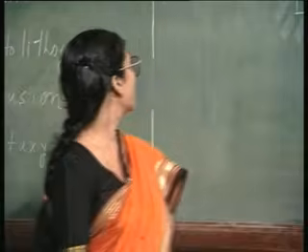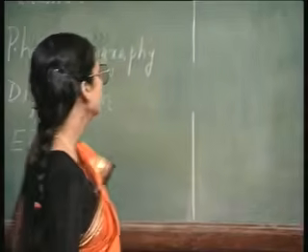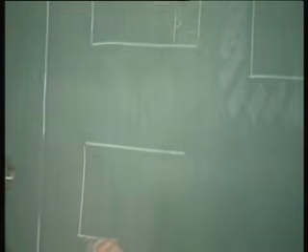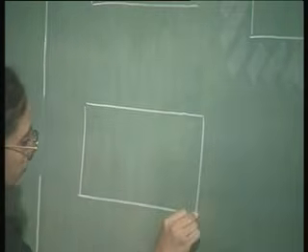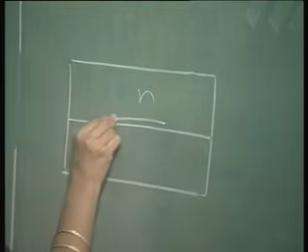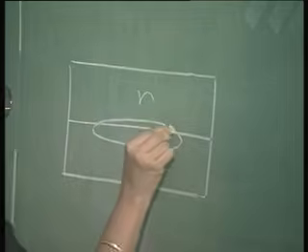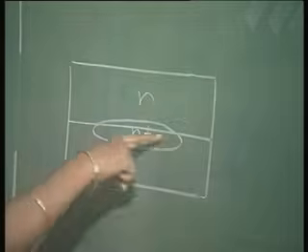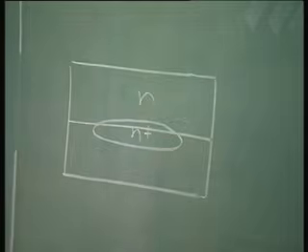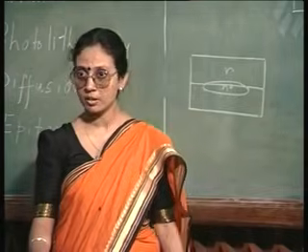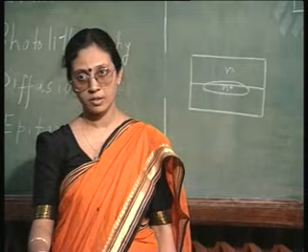In order to have the PN junction isolation, what we do is something like this. You have the N epitaxial region and the N plus region. This is for one transistor. Similarly, next to it you have another N plus buried layer diffusion and the continuous N epitaxial layer.